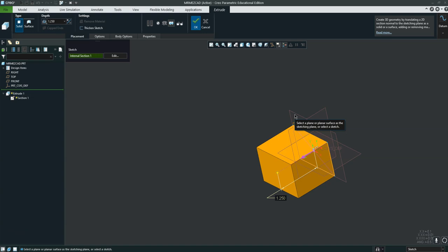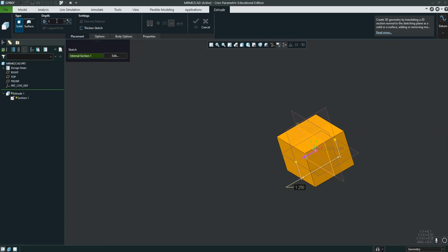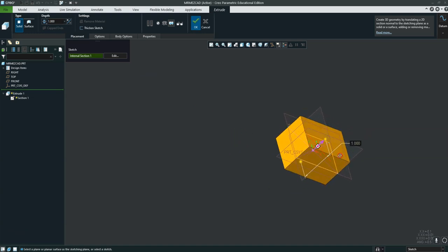It's also just a better way to model when you have symmetric things. So we're going to come up here, we're going to say symmetric, which is now going to center it, just like that. And no matter what I change this number to, it'll stay in the center. The number we want, as I mentioned earlier, is 1. So we're going to type 1 up here, we're going to hit enter, and now your block should look like this.